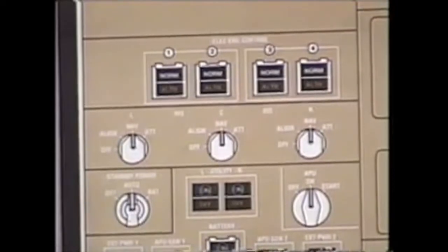If the center IRS was to lose AC bus 1, it would go to the APU hot battery bus and run for 5 minutes and then shut down. If the left or the right IRS was to lose its respective AC bus, it independently can also go to the APU hot battery bus and will run for at least 30 minutes, depending on the availability of your service bus. If your service bus is available, the battery chargers will actually run these two IRSs indefinitely. If the service bus is not available, the APU hot battery bus is actually draining the battery, thus the 30 minutes. Doing an external walk around, you can tell if an IRS is switched over to the APU hot battery bus by the continuous horn from the nose wheel well.